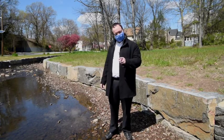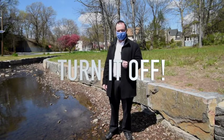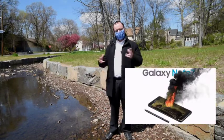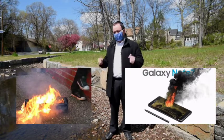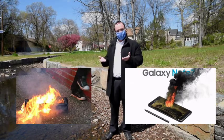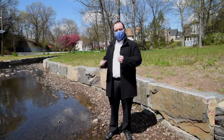So, just as a general rule, if you find electronics that are overheating heavily, turn them off. I'm not sure if you guys are up on the latest news, or this isn't even the latest news, this was quite a while ago. Remember when the Samsung Galaxy Note 7, I think, kept blowing up? Or when you had the hoverboards made by rip-off companies that kept blowing up? That was because something in there short-circuited, right? And what happened was that it just built up heat. It wasn't doing anything besides heating itself up, and then it caught fire. And when lithium batteries catch fire, it can burn for days and days. It's extremely hard to put out, and it can be highly explosive.